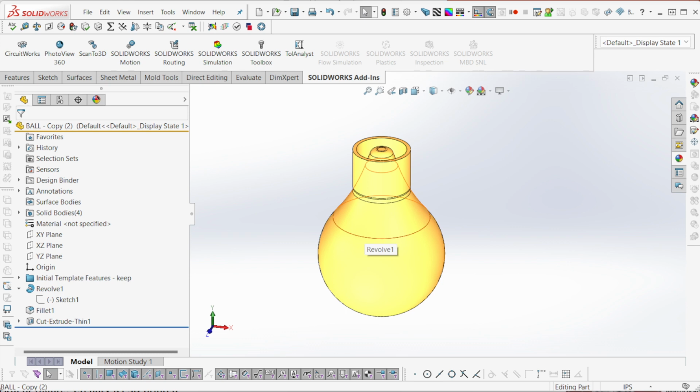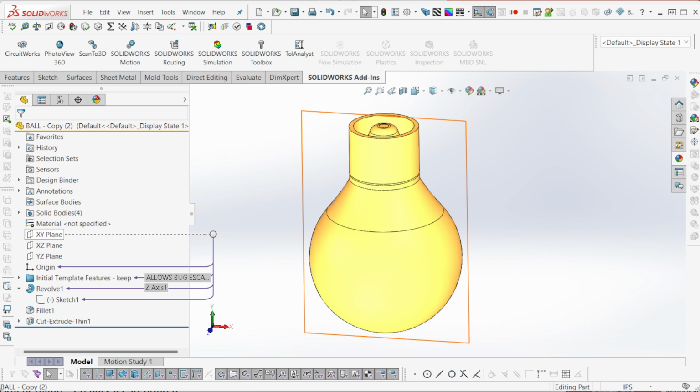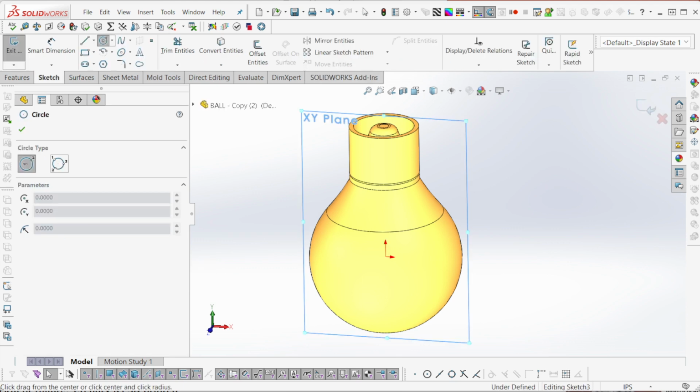Exactly, a modeled cut does not get hatched, and the shaded sections don't get hatched. So if I have the shaded color model and I want to do a cutaway that's hatched, there's no automatic way. But I'll show a pretty easy way to do that. I'm going to show it two ways.